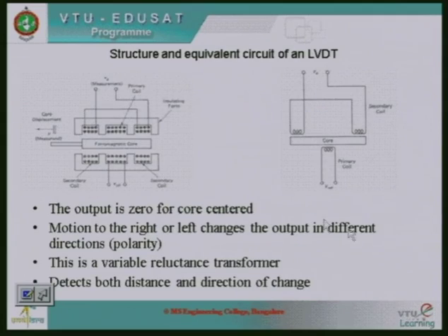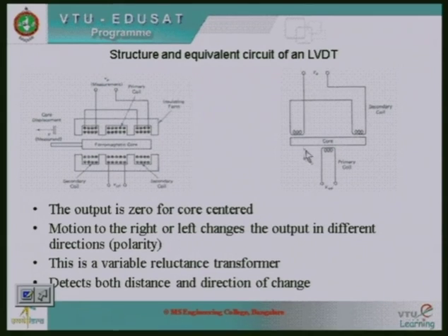So this is the circuit diagram for LVDT. You have a primary coil here, then the core, then two secondary coils. The voltage is taken across the secondary coils. Whenever you apply voltage here, the core position decides what voltage is available across this. If the voltage here is positive, it implies the core is placed here. If the core is slowly moved out, the voltage here would become negative, indicating that there is a displacement happening on the core. So the displacement is now converted to a voltage, and that is the logic of LVDT.